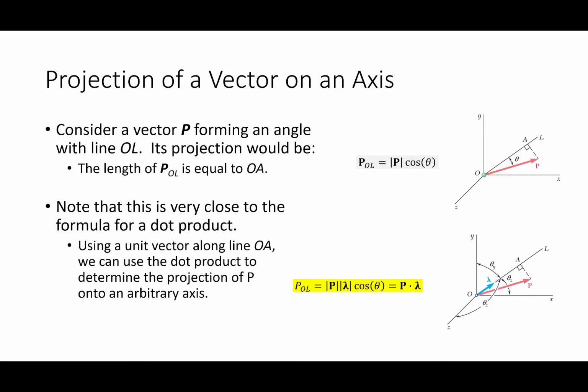Okay, so the 200. What does the 200 mean? The 200 means the tendency to rotate about the x-axis, right? And I propose that that tendency is described by 200 Newton meters. That's the torque, as it were. And so what's the direction? Right-hand rule. My thumb points along the x-axis. So this moment vector is saying I want to rotate about the x-axis in that direction, an amount of 200 Newton meters.